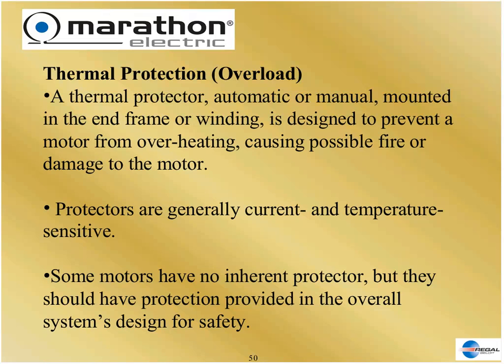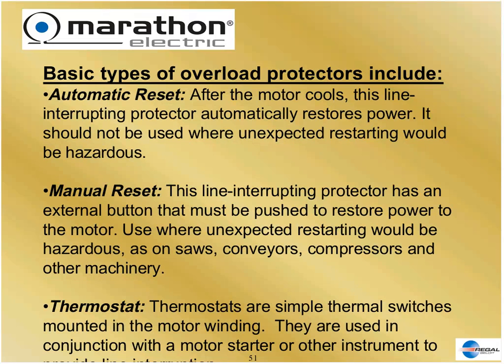And burning up the motor is not a particular problem. We can always get a new motor, but we certainly don't want to cause a fire if the motor were to burn up. So we use thermal protectors, especially in single-phase motors, for that purpose. Thermal protectors will generally protect the motor, and its intent is to prevent it from causing a fire. There are basically three types that are used in the industry.